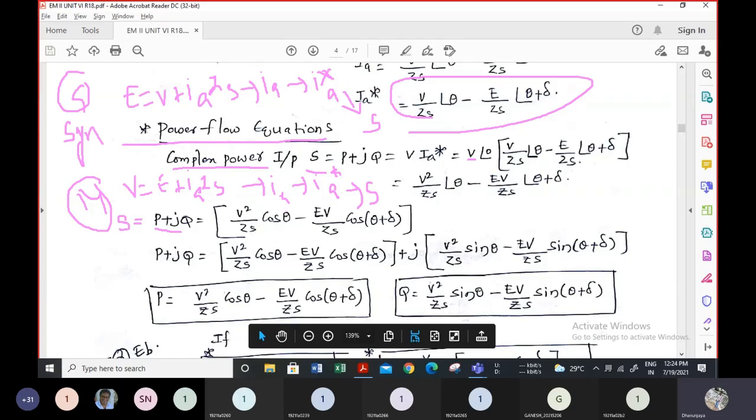So now we have the total term here. Now I will split the terms into active power and reactive power. Whenever we have an apparent value, if I multiply with the angle cos, then it will be the active power. If I include the sine terms in that value, it will be reactive power.